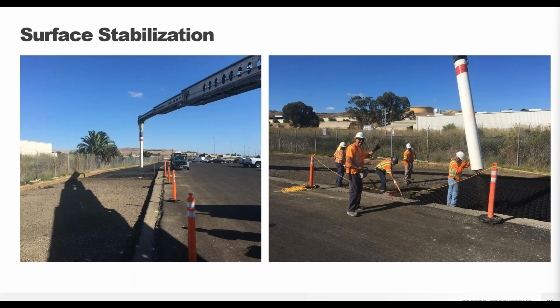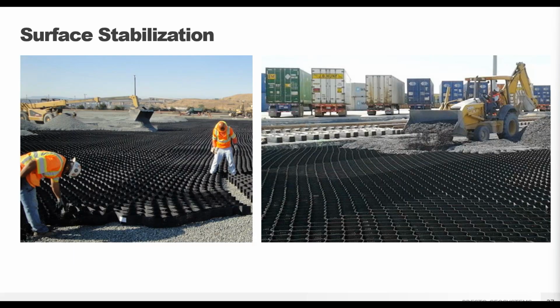There are many ways to place the infill, and a rock slinger is one of them and allows precise placement for fast, even filling while controlling the height from which the aggregate falls. Buckets with extendable booms can also be helpful, though a push with a dozer or backhoe will work just fine.